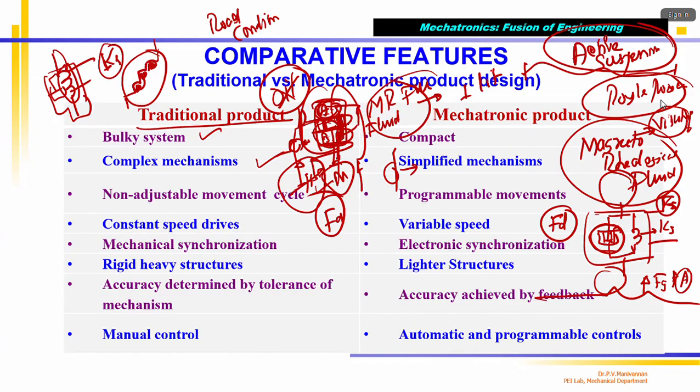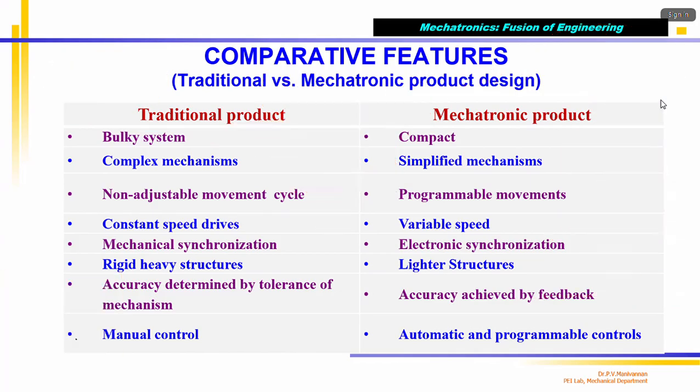So the damping force of the damper is changed by controlling this, but it uses a special magnetic field. We will see that when we talk about this. Right now, note this point. So now the thing is non-adjustable movement. By varying the damping constant, I can say at what rate the piston of the damper is moving. So the vehicle sprung mass movement can be controlled, correct? Which is not possible in a conventional damper. That's why it's a non-adjustable movement.